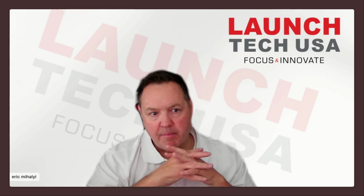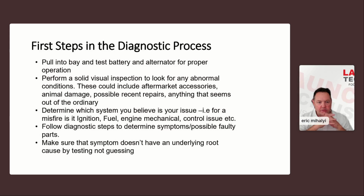So the next step, and I can't tell you how important this one is: pull into the bay and do a battery test, right? First, we'll talk about the battery, right? So the battery test is so important on a modern car. Why? What does every car have nowadays on the negative battery terminal? They have a battery sensor.